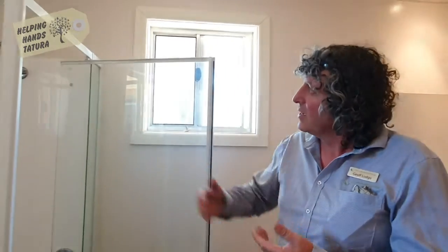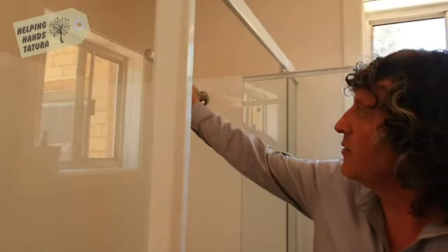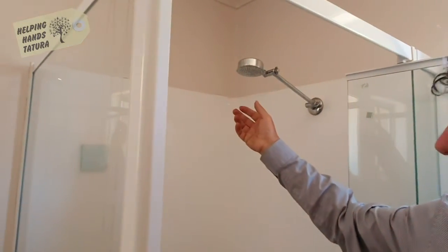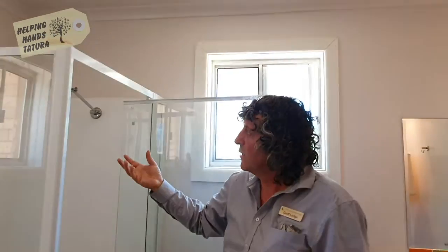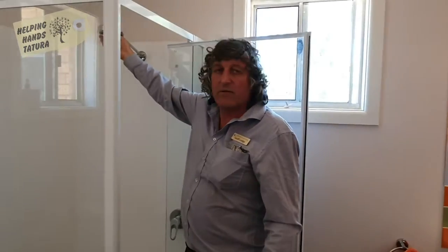A thing to be mindful of in terms of energy efficiency is the amount of energy that is embedded in heating the water for your shower. So if you can adopt water efficiency, you also reduce the amount of energy that you're consuming. So when I have a look here, and I look at this shower rose here, very effective, very comfortable, and uses a lot of water. You can get water efficient roses to replace that, and you'll reduce from around 10 to 12 litres per minute down to about 3 to 4.